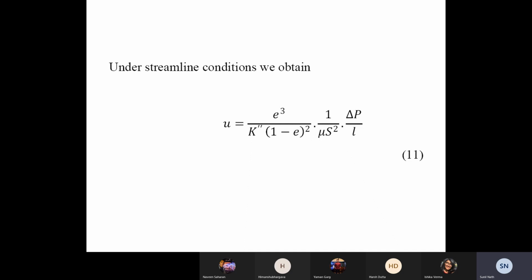And so then you should be able to calculate, just like we did for settling cases. For free settling, then we had a correlation for hindered settling, and now we should be able to calculate everything: velocities, drag force, pressure drop across a packed bed if we know the lengths and surface area and the flow hydrodynamics region. Okay.